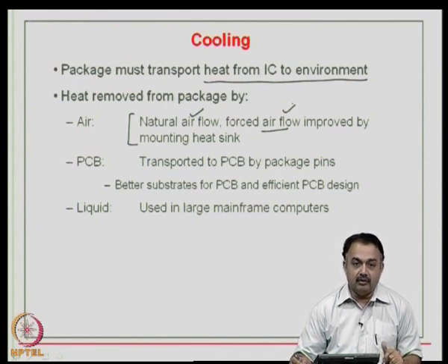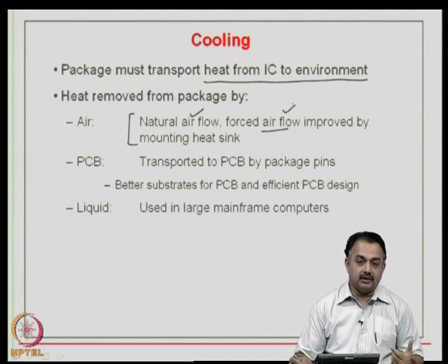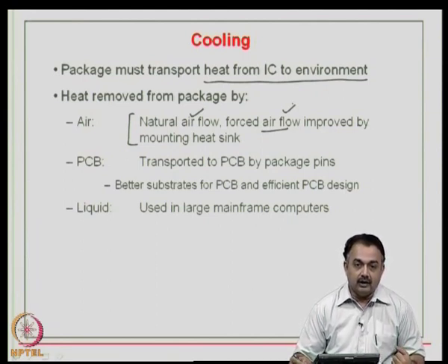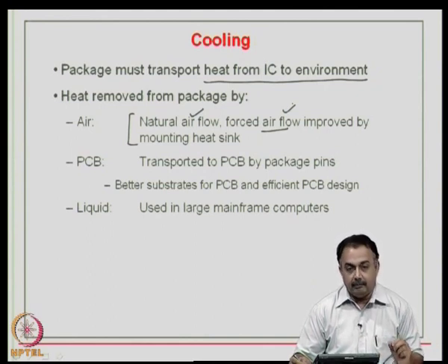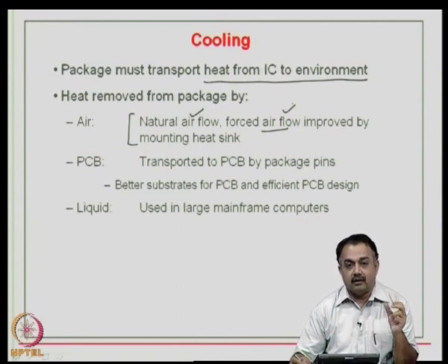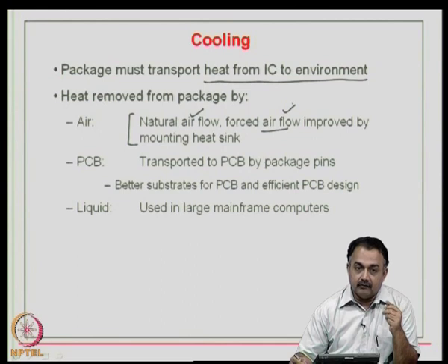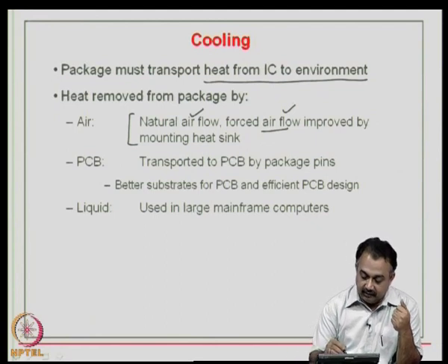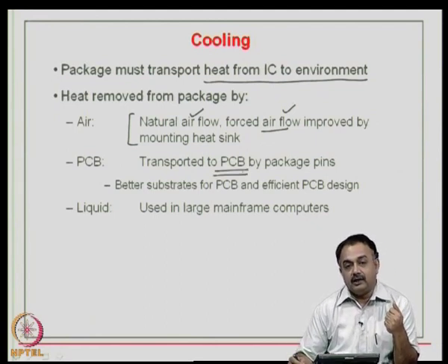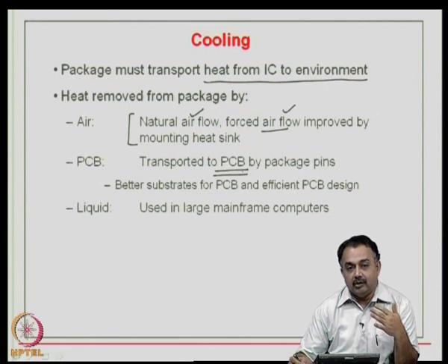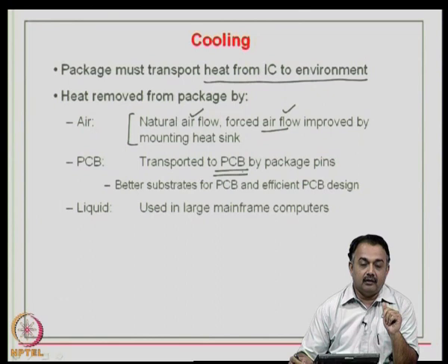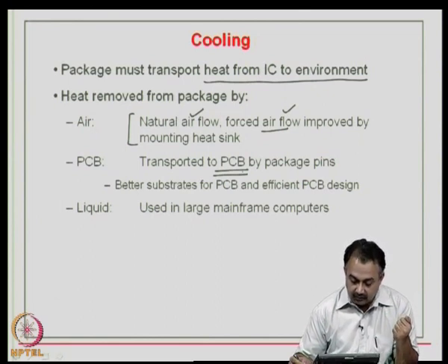Now, the printed circuit board or the PCB on which the components are mounted, on which the packages are mounted, will also have to behave as a heat sink. Therefore, the package pins, the leads or the solder balls in the case of a BGA or a CSP will have to transport this heat to the PCB, so that the heat at the die stage is quickly moving through the package substrate, through the package pins, and then to the PCB on which the host of components are assembled or mounted.